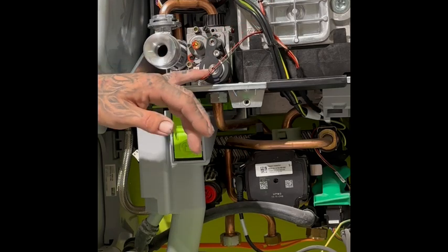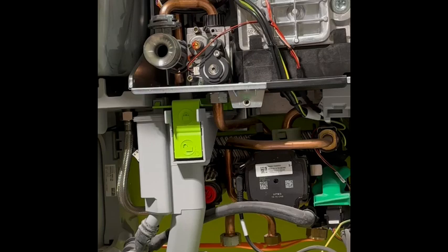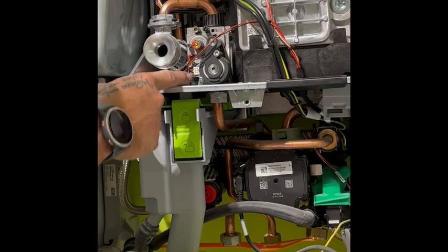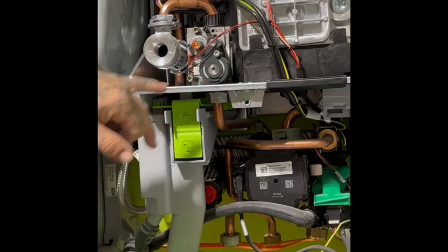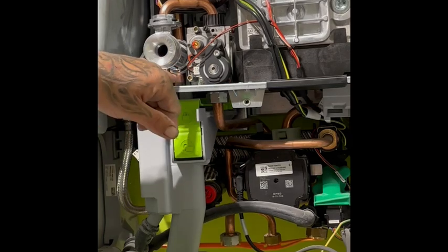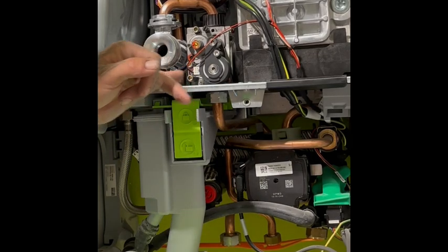On this particular boiler, that's going to be a low voltage ignition, if I remember rightly. So let's work down the gas route first. We need to know the gas valve opens and we've got voltage to it. So we measure that from P1 of the gas valve. And we'd also take a voltage reading from there, if it's readable. Obviously every boiler is